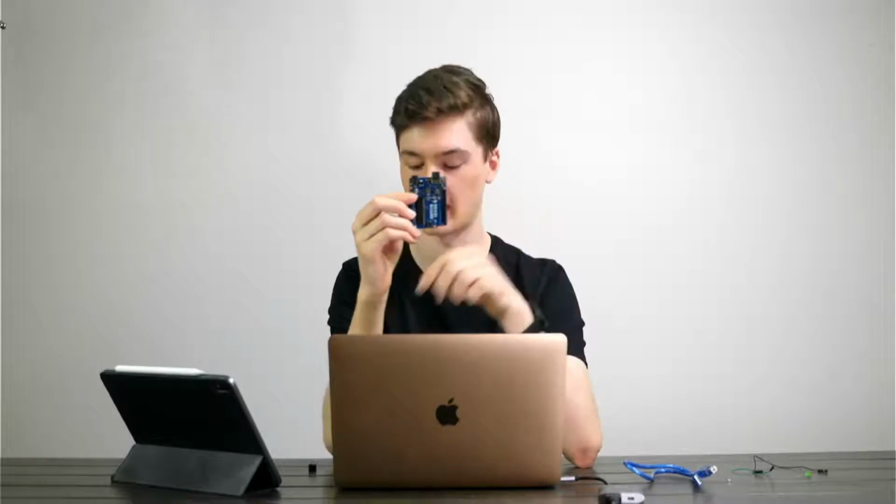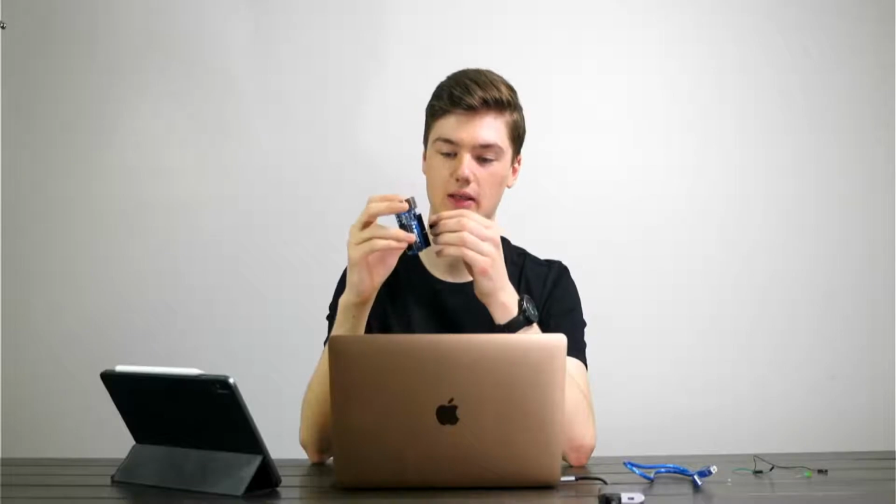But we have our brainboard. You'll notice that along the side of the brainboard, we have different numbers. These label the pins for the board. Now, we want to get the long leg of the buzzer and put it into the pin that says 11. You can count up from the bottom where it says 8, then you go 9, 10, 11.